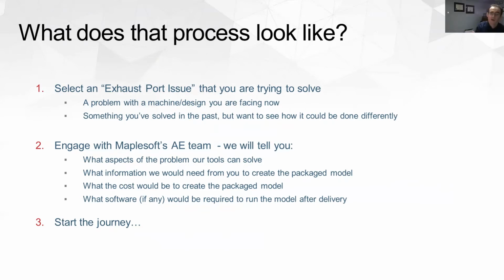And so we built the model for them. And actually, in this case, it turned out that there were spikes that they hadn't gotten from their analysis they'd done in their Excel, sort of the static analysis. And they were able to say, there's some things we can change in the motion profile to remove those torque spikes and increase the longevity of the motors on the machine.